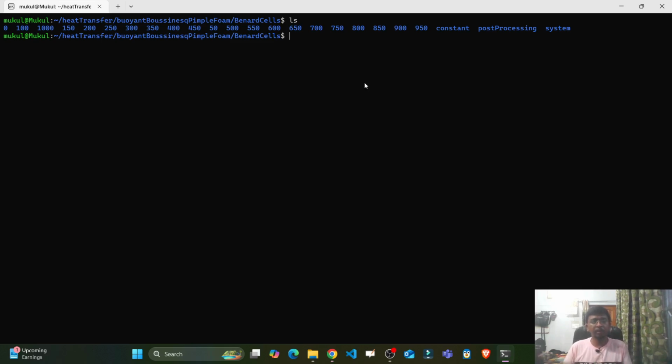So let's see the results in ParaView. For seeing the results, we have to first make a .foam file. Then we have to go to paraview.exe foam.foam. Enter. It will take 1 or 2 seconds to open.